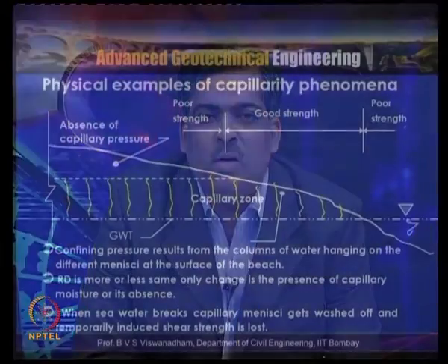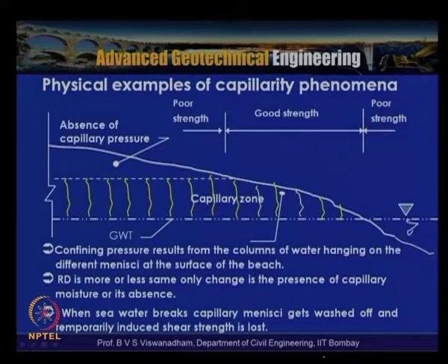So in the capillary zone, when the water is less, let us say all the sand particles are covered with a thin film of water, which creates what is called a negative pore water pressure. This negative pore water pressure pulls the particles together, and if you look into the effective stress